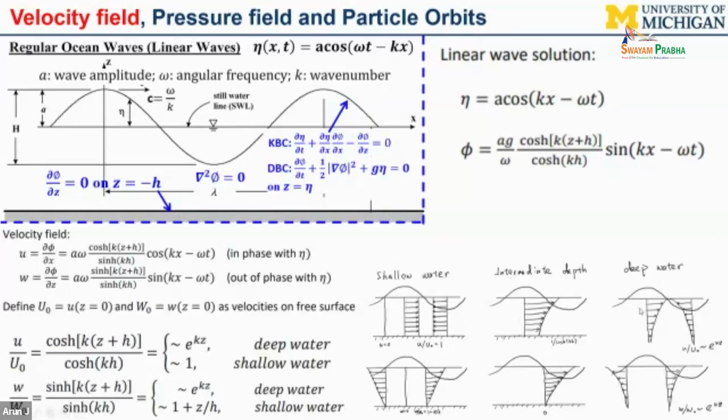For example, you know the surface amplitude A is the surface motion. With depth, this wave is transferred in the x direction and z direction, however the amplitude will change. With deep water, take z equal to half of the wavelength. For example, if the wavelength is 80 meters, half will be 40 meters.